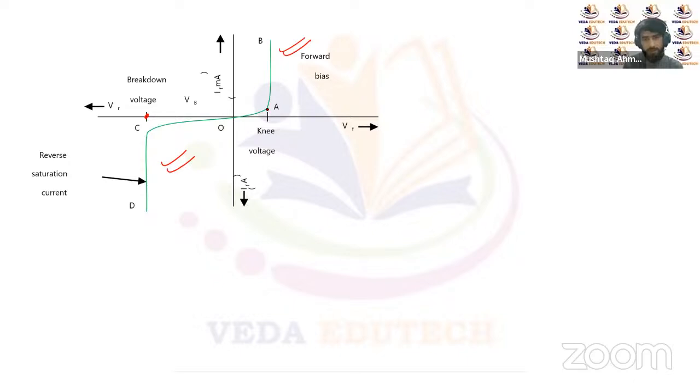And here this voltage we call the knee voltage. At this voltage the forward current increases exponentially, right? This voltage is actually equal to the barrier potential, right? So if we apply the forward bias equal to the knee voltage, then at this point the forward current will increase exponentially, or the barrier potential will be removed from the junction completely, right?